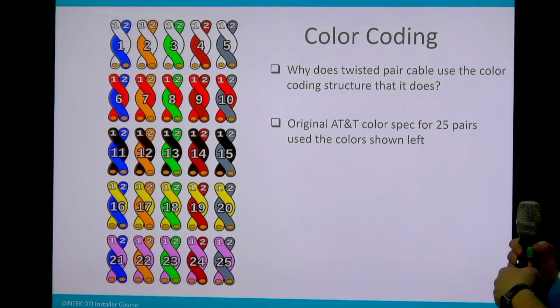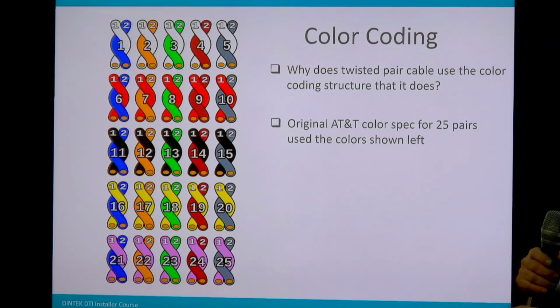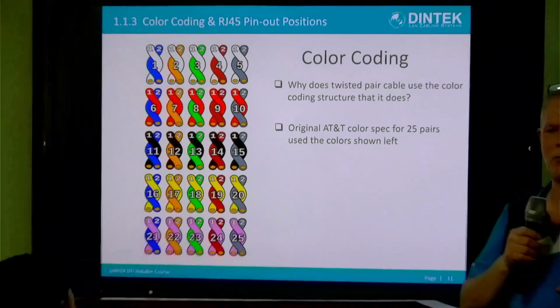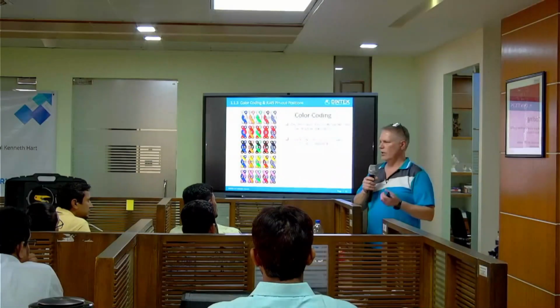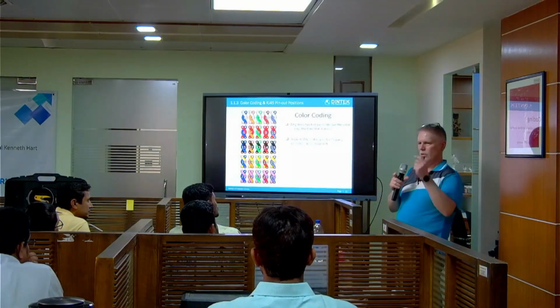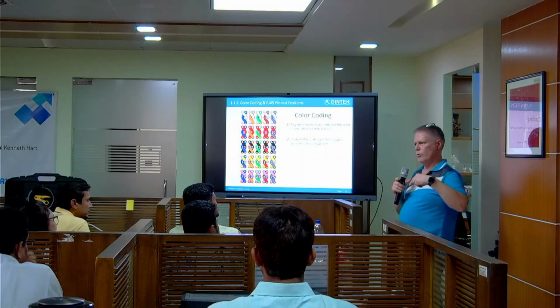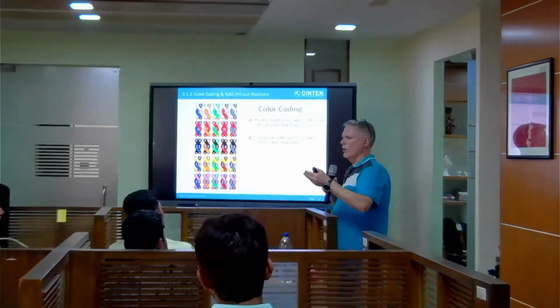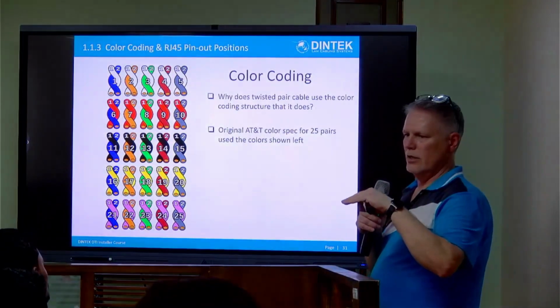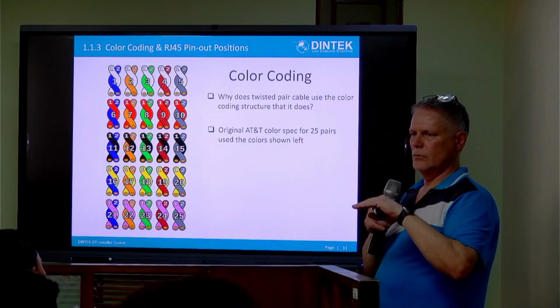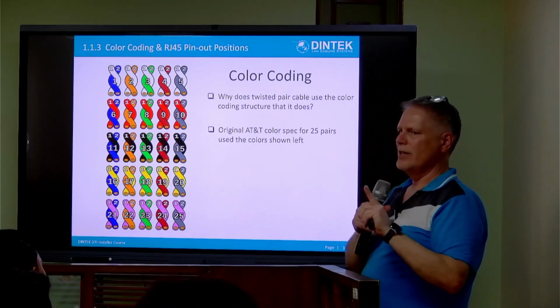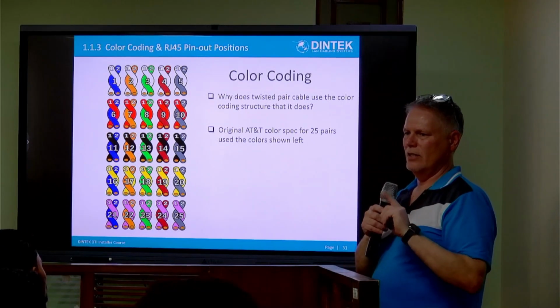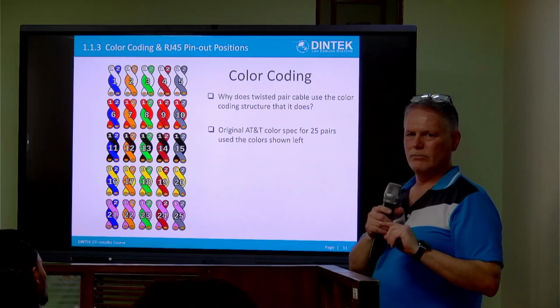When it comes to referring to pairs and cable, if I said to you, we've got an open circuit on pair 1, I'm always referring to blue pair. If you use wire map testers, which has coloured lights which cycle down, testing the different pairs, if you have an error come up on, say, the third pair, it's going to be the green pair. As long as it's a T568A connection.